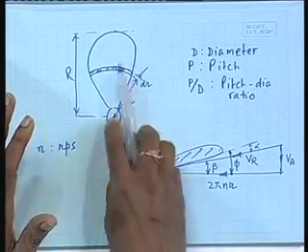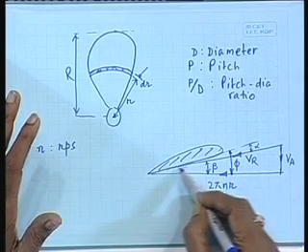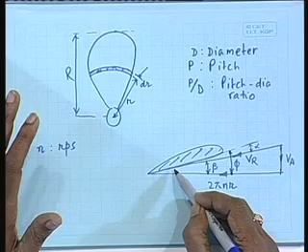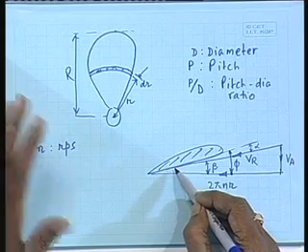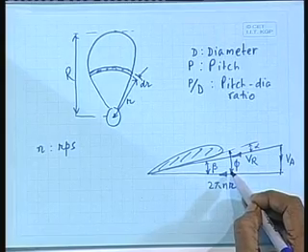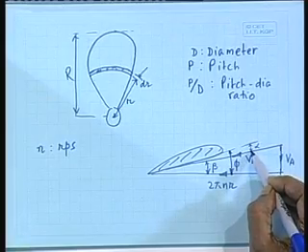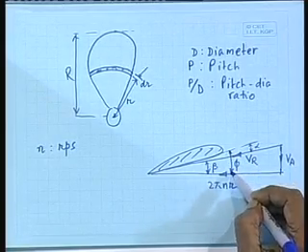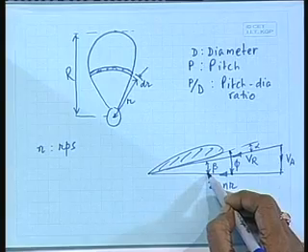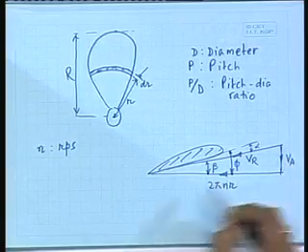Yes, sir. Right. Then the resultant of these two velocities is V r, which is now impinging on the propeller blade. Okay. If you take the rotational velocity and axial velocity both into account, then the resultant velocity is not at an angle phi, the pitch angle, but at an angle smaller than that, and the angle of attack alpha is equal to phi minus beta, where beta is tan inverse of V A by 2 pi n r.